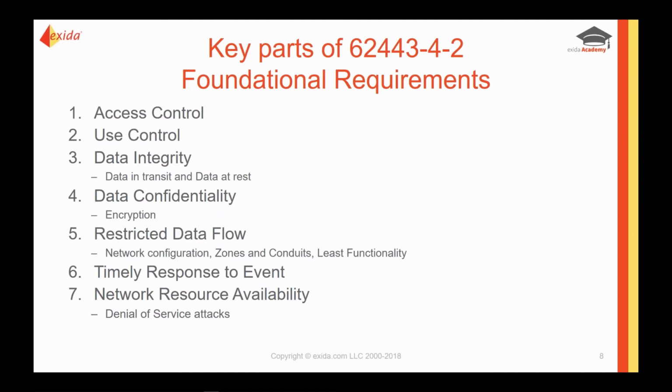partitioned, such that if there is a denial of service attack, the bandwidth required by the communications does not keep your control algorithms or your control strategy from running. You may lose external communications, but your key control functionality still operates correctly. So again, this impacts the design of your system and building systems that can tolerate these attacks and yet still function correctly. So these are the 7 basic foundational requirements that individual products and components should have, as well as should be part of general system level design.